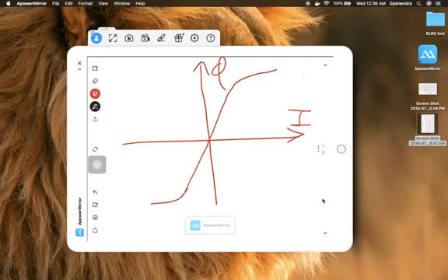If you see carefully, in the linear region the slope is higher in the magnetic material when there is no air gap. As a result, you have higher inductance. But with very low current flowing into the inductor, it can go into the saturation region.